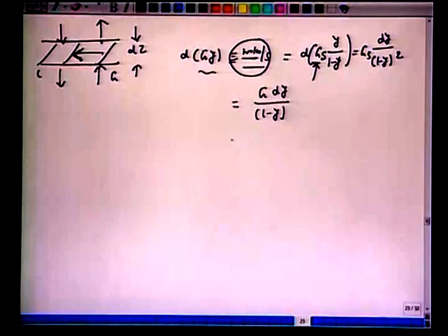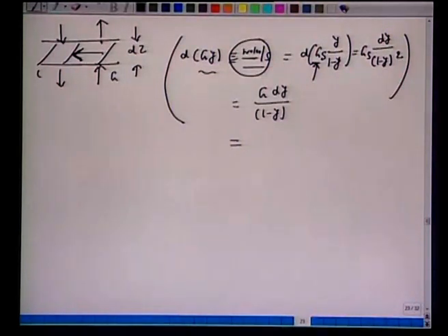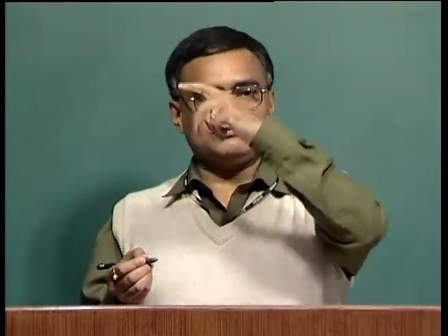But remember, the entire quantity which we have calculated and written in different forms can also be written in terms of the liquid phase. Whatever happens in the gas phase in 1 second, if 5 moles change across this dz, the same 5 moles will appear in your liquid phase. So, that is a species balance. Under steady state, there is no accumulation. So, if the gas flow rate is 5 here and 2 here, what has happened to the 5 to 2? 3 must have gone into the liquid phase. That is the balance we are trying to make.